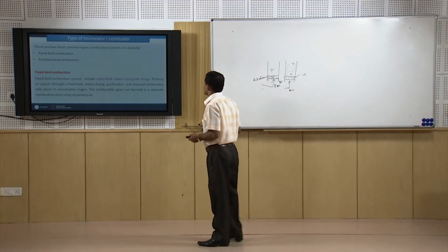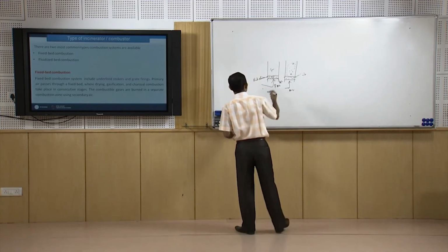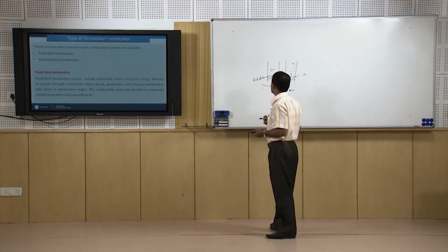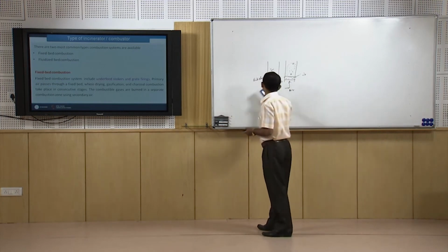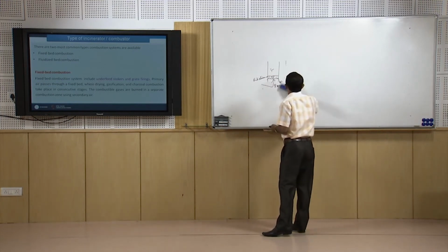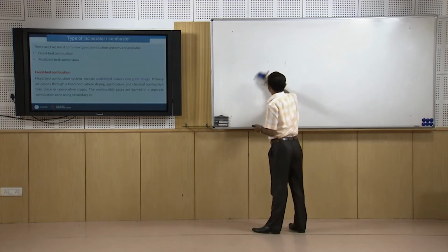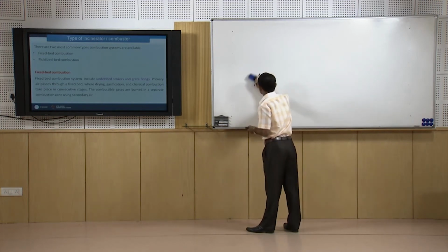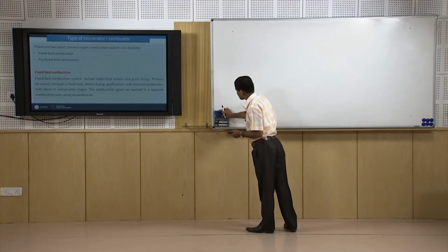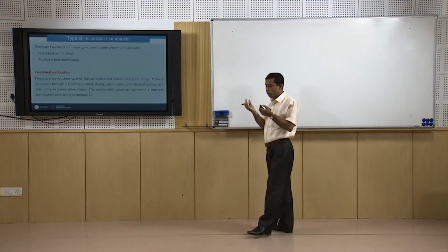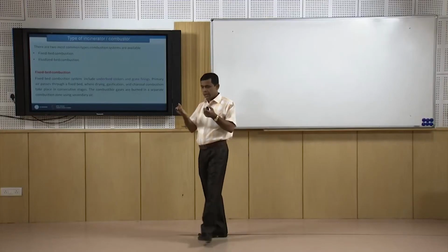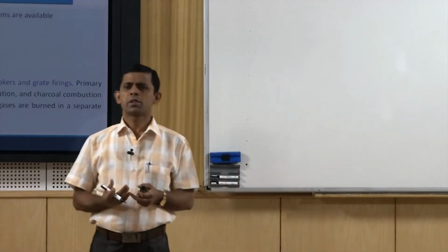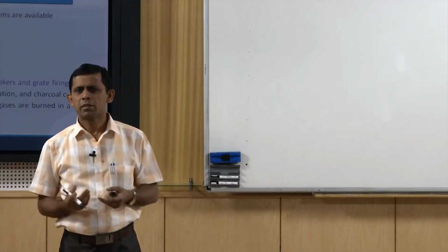But now how does the fixed bed incinerator work? Obviously we have to put the feed inside the incinerator. So, one feeding arrangement will be there, and we have to hold the material inside this combustion zone for say 30 to 45 minutes or even 60 minutes.